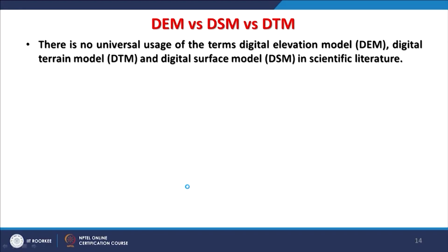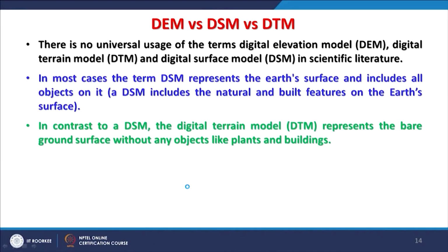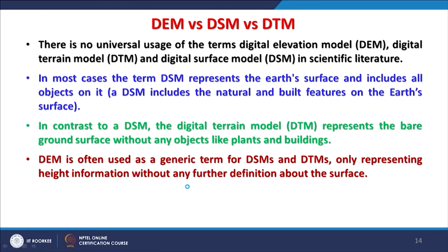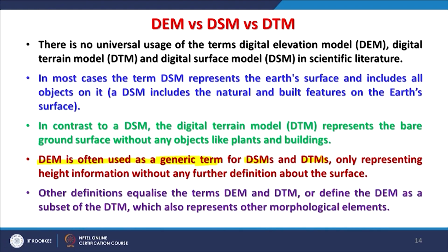Now, of course, there is no universal usage of the terms digital elevation model, DTM or DSM in scientific literature. Sometimes people use them synonymously, but as I have explained, all three terms are different and one should not get confused after this discussion. We have already discussed what DSM and DTM are. DEM, as I have already said, is a generic term, a common term for DSM and DTM, but DTM and DSM are also different surfaces.